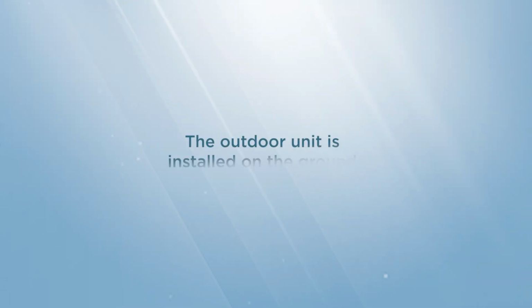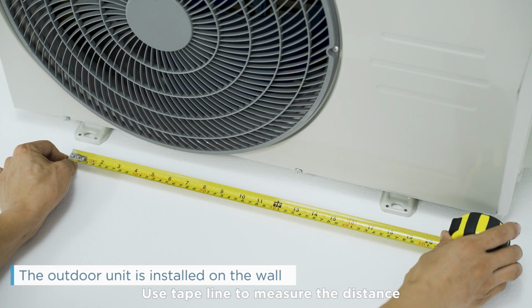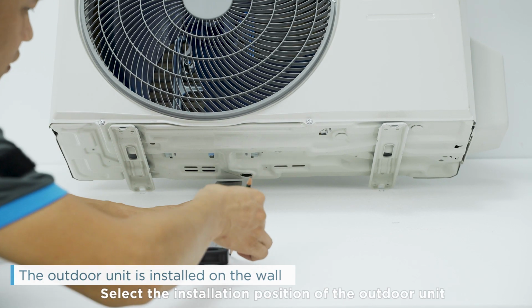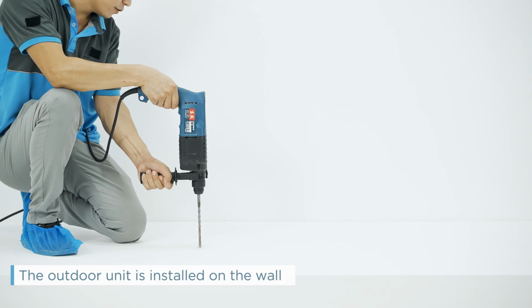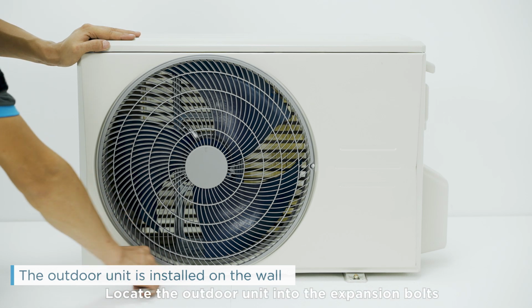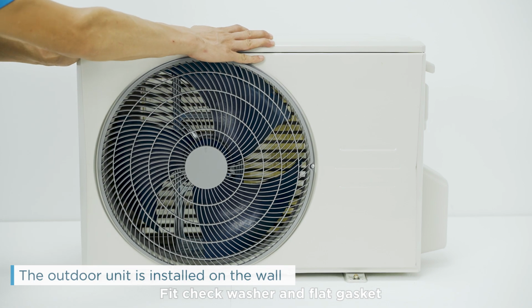The outdoor unit is installed on the ground. Use tape line to measure the distance between the footing of the outdoor unit. Select the installation position of the outdoor unit. Note that an L-shaped sink should be set in the drain hole of the outdoor unit for drainage. According to footing distance, drill into the expansion bolts. Locate the outdoor unit onto the expansion bolts. Fit check washer and flat gasket.